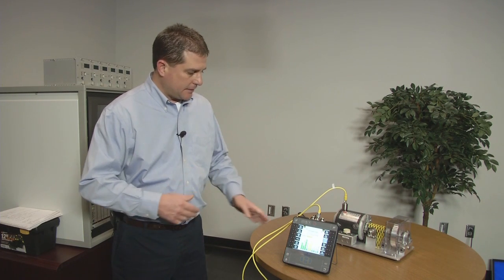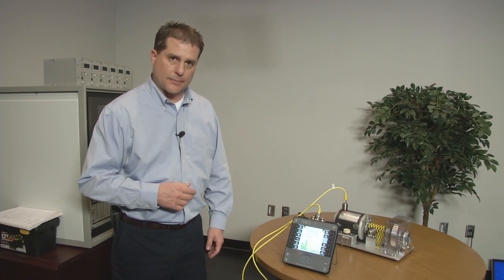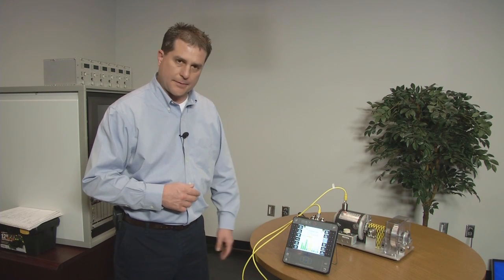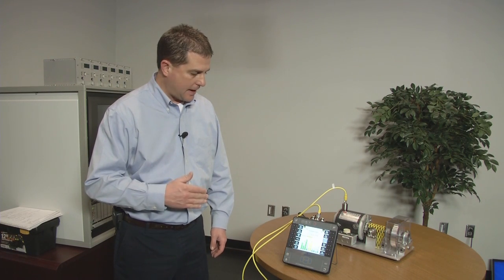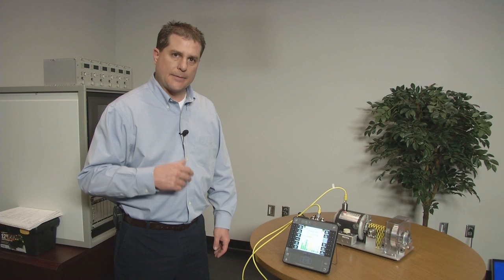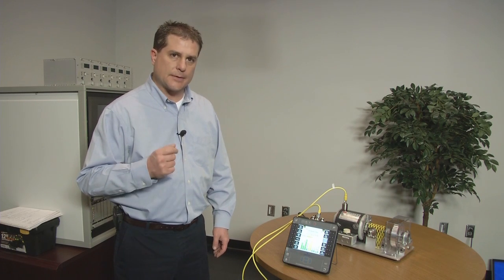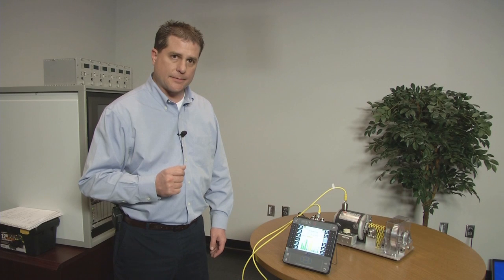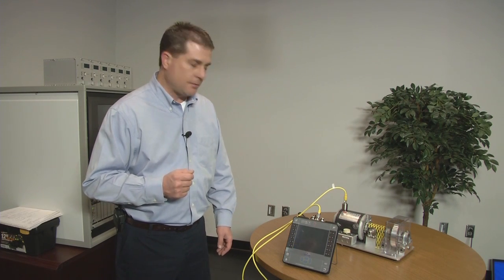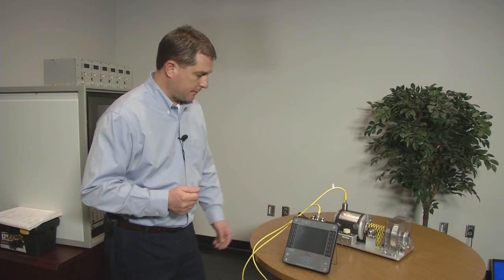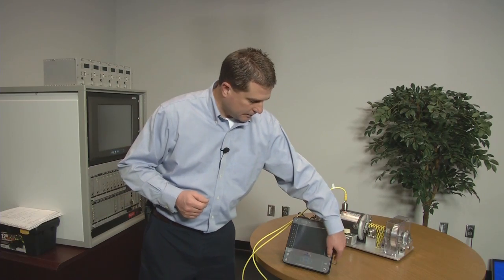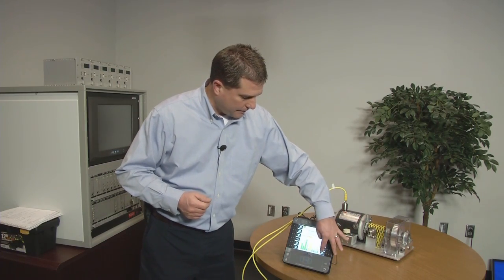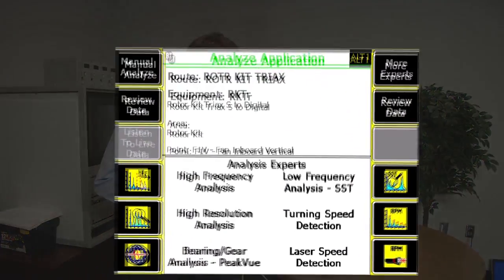And so let's say you're out in the field, you collect some route vibration, and you see some alarms on the screen like I've got here. I've got high 1 times, high 2 times. Well, is that looseness? Is that resonance? Well, we could go and do a running bump test with negative averaging to determine if we've got resonance on this machine. So what I'm going to do is come over and press F12, Run Analyze,